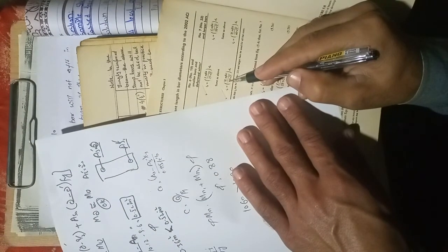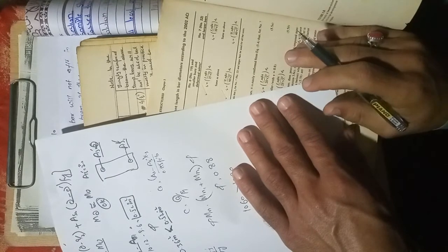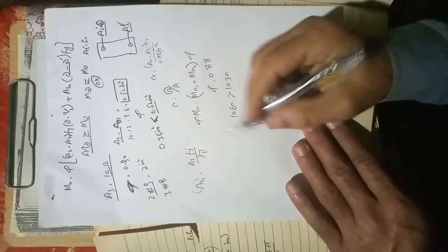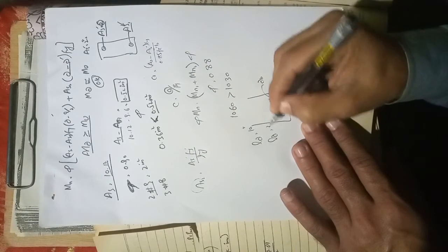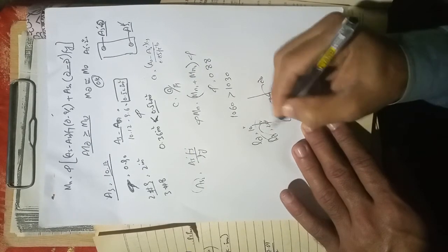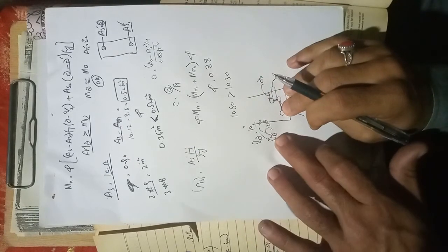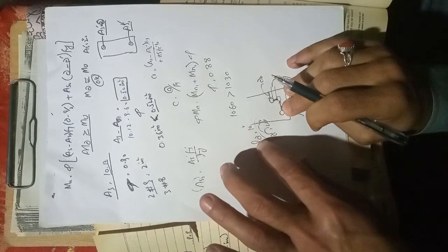Here you are dividing by 50, increasing the development length, and here is the decreased value. If your development length is increased, like say 10 inches versus 20 inches, it is difficult to adjust in the beam section, while the smaller one is simple to adjust.